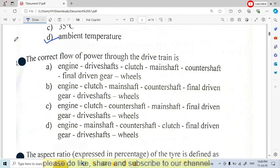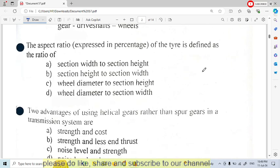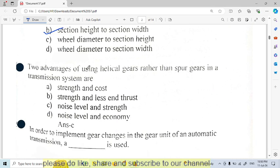Okay. Next question is the correct flow of power through the driven drive train. So the correct flow of power is engine, next clutch, main shaft, counter shaft, final drive, final driven gear, drive shaft, and wheels. So option B is the correct. Next, the aspect ratio, expressed in percentage, of the tire is defined as the ratio of the section height to the section width. Option B is the correct.